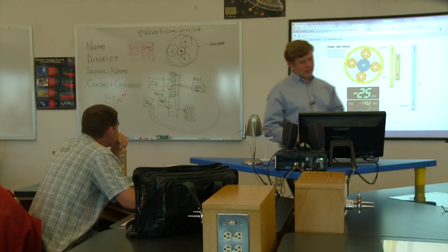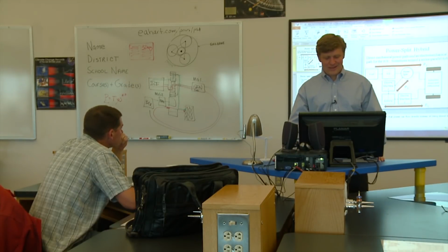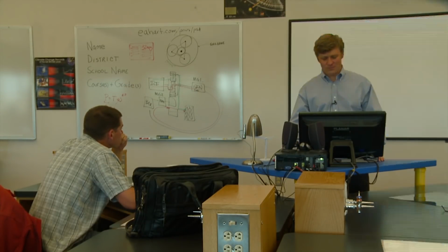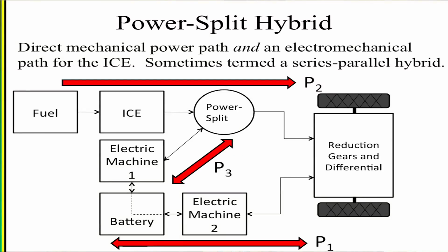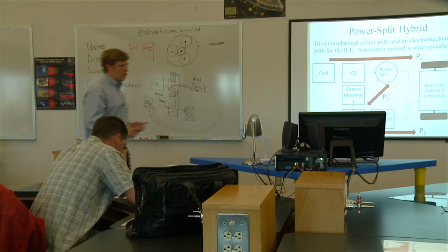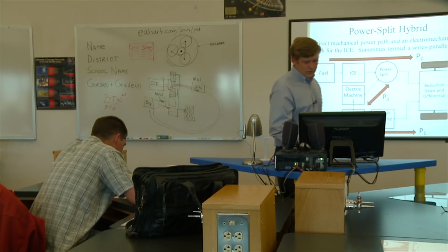Now, in our topologies of hybrid electric vehicles, we don't necessarily say that this has to be a power split epicyclic gear train. You can do it with all sorts of other things. It's common to have power split with hydraulic hybrids or anything else. You can have power electronics that do a power split. The Prius is just obviously the most well-known example of that sort of thing.